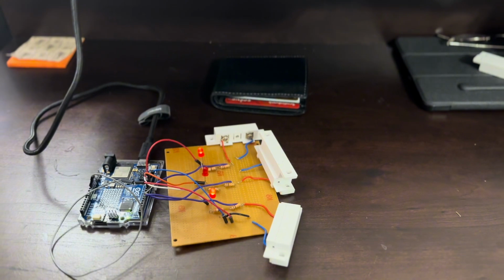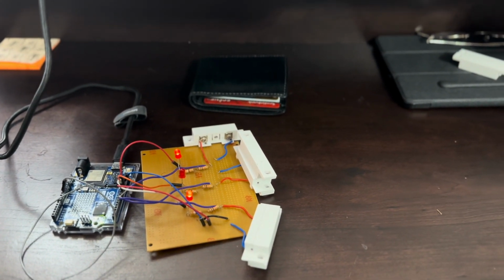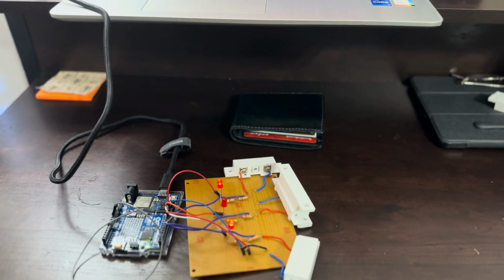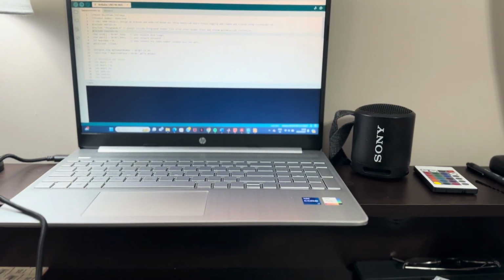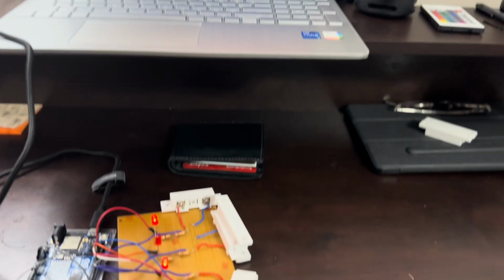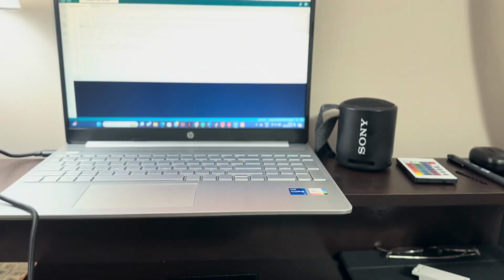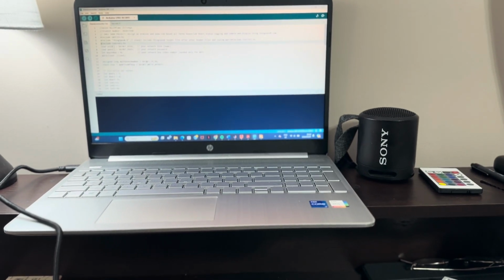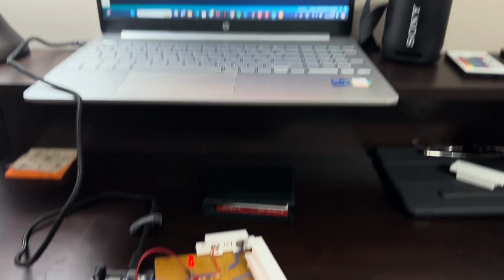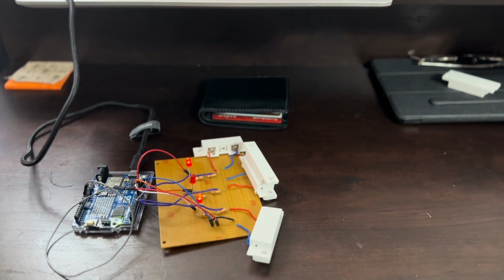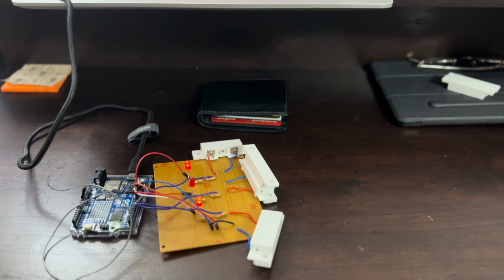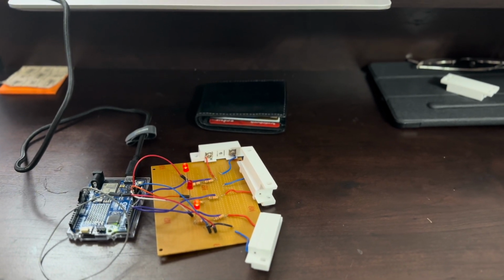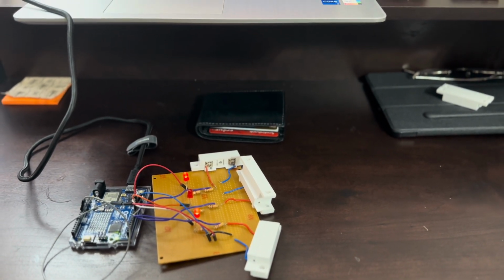So, when the status of the door is changed, the Arduino Uno R4 Wi-Fi model and the Arduino Uno IDE registers or retrieves data of the change in status, and it reflects this data to thingspeak.com as well as physically, to just cross-check to see if my doors are functioning. I use the LEDs to go on and off to show the status of the doors.